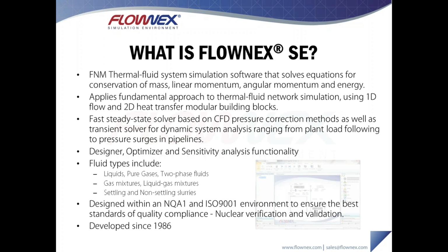The software itself also includes a bunch of other analysis tools. So we have a designer. This is similar to the goal seek inside of Excel. You provide target values for results that you would like and a set of inputs that Flownex can vary, and it then varies these inputs until it achieves those particular results. Our optimizer works in a similar way, except instead of a target value, we either look to minimize or maximize a particular value.